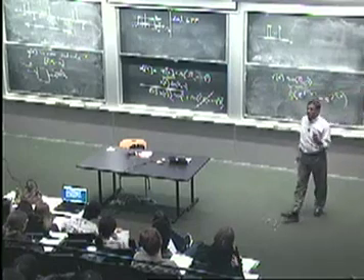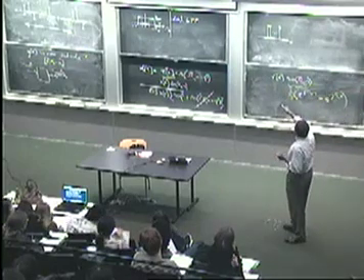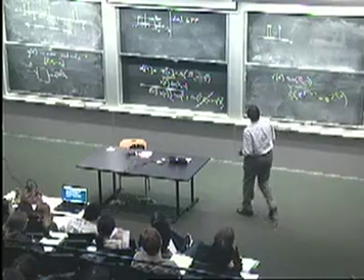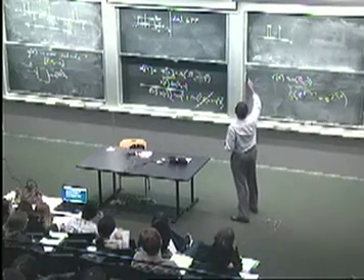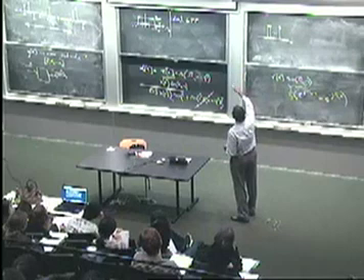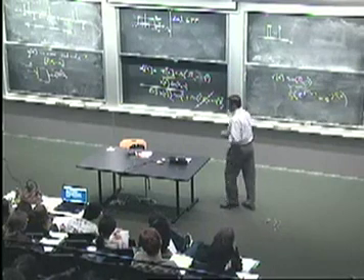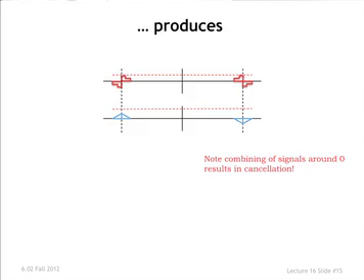But the interesting thing is that the two replications, when you sum them up, will leave you with nothing at 0, because this piece here will cancel out exactly with that piece there. So if you think through in the spectral domain what's going on, you'll understand exactly that if you've put your signal on a cosine and you demodulate with a sine, you're going to get nothing in that low-pass region. So that's just the same result, but seen spectrally.